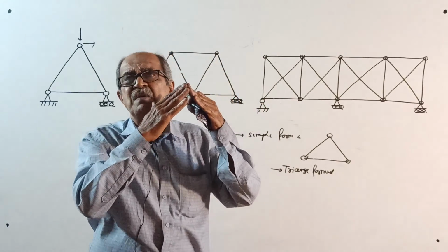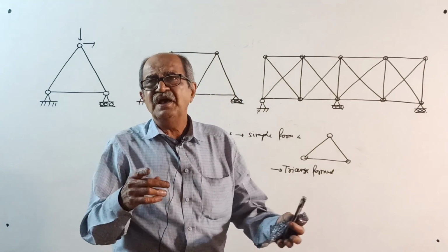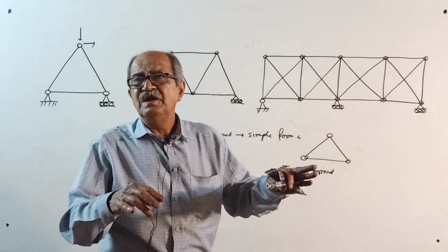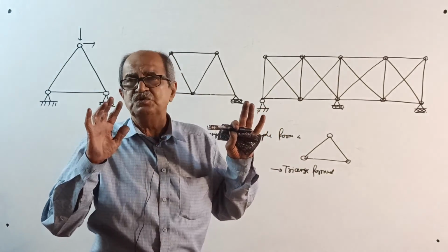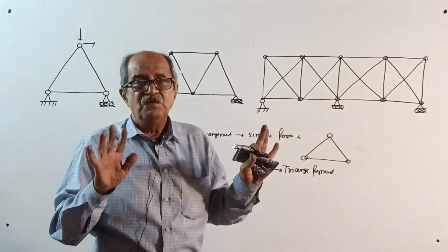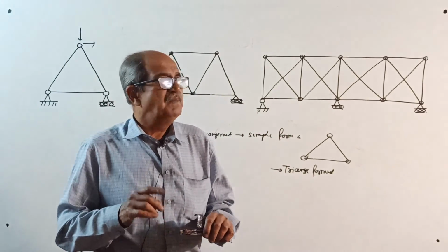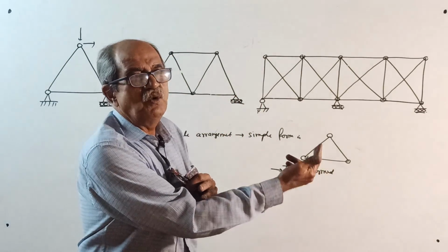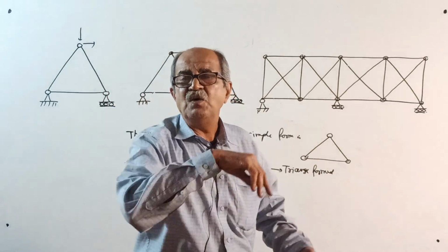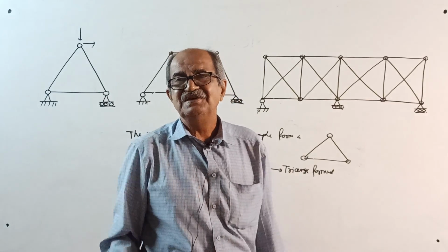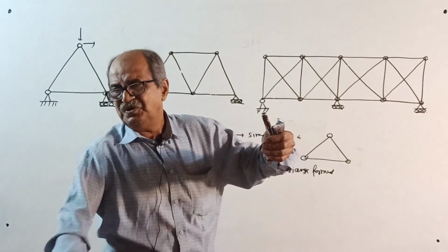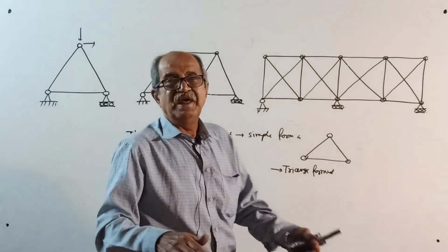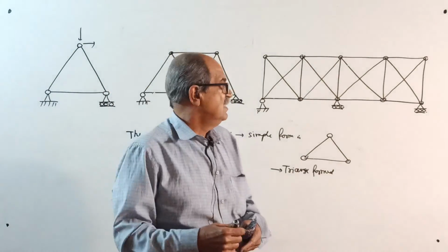Two legs you can't imagine. Four legs, it is very difficult to put the tripod. Two legs is unstable. Four legs can be stable, but very difficult to align. When you align this way, that will come out. When you align these three, that will come out. But three legs, very easy, just put it anywhere you want. It will automatically take care. You can have different elevations, nothing. So remember,